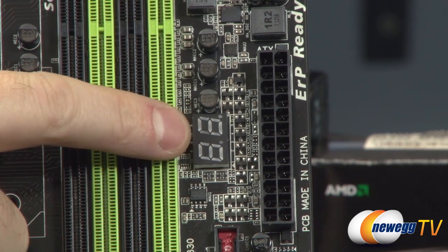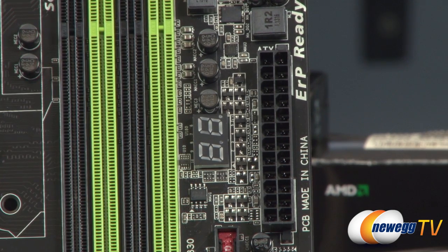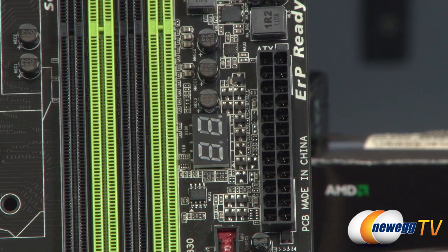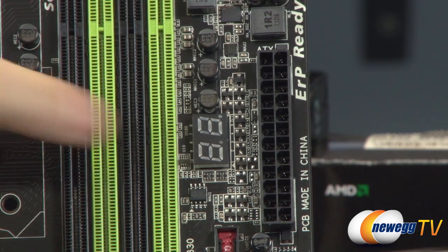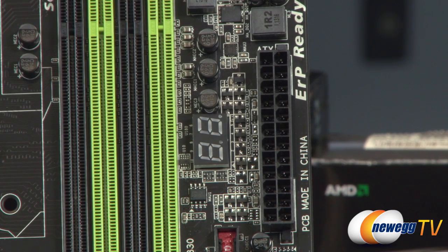This little debug LED will show a series of codes as it is going through each step of that process. So if your computer is suddenly stopping and restarting itself over and over again, you can look at that debug LED, see what code is listed out there when it does that, and maybe it says, oh, it's a RAM initialization thing it's going through. Then you can have a much better idea, well, it's probably, maybe my RAM's not seated correctly, or maybe I'm using incompatible memory, or maybe I'm using the wrong memory slots, something like that.